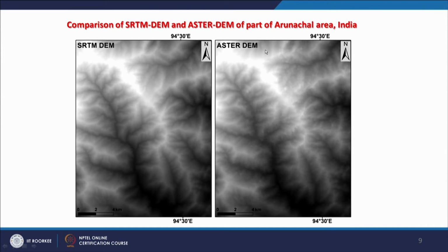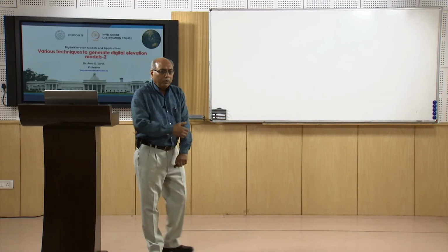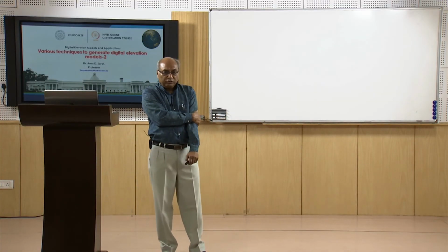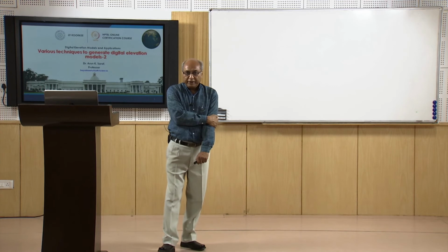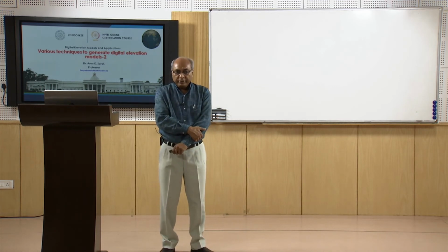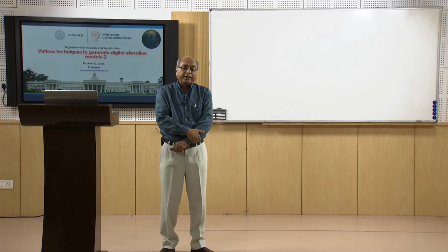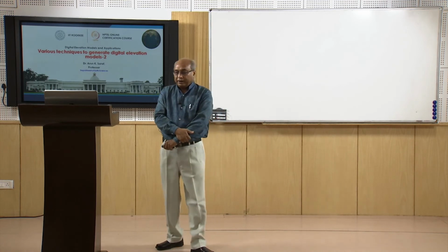And in case of Aster DEM, the stereo pair technique, which we have just discussed briefly, has been employed. But the products which have been generated look very similar, at least at the visual level. If we go further, we find that SRTM is not good for hilly terrain because it employs the SAR interferometry technique, and radar remote sensing has some problems in hilly terrain, especially in the Himalayas, which is highly rugged terrain. But for plain areas, SRTM is good.